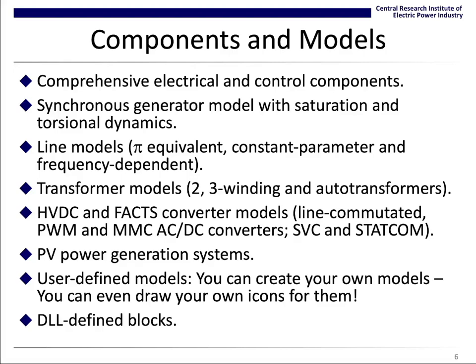This slide shows components and models included in XTAP. XTAP has comprehensive electrical and control components which are necessary to build practical simulation cases and user-defined models. It has synchronous generator models with saturation and torsional dynamics.